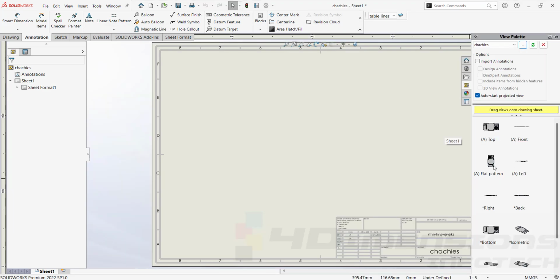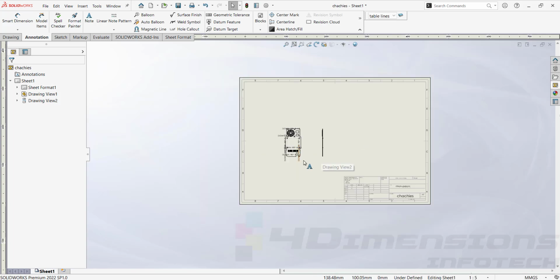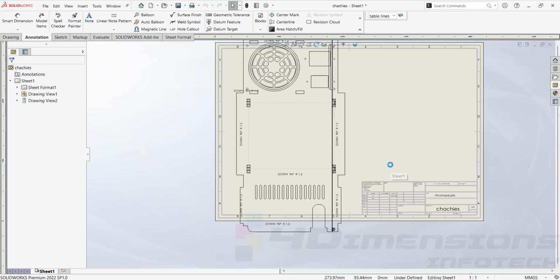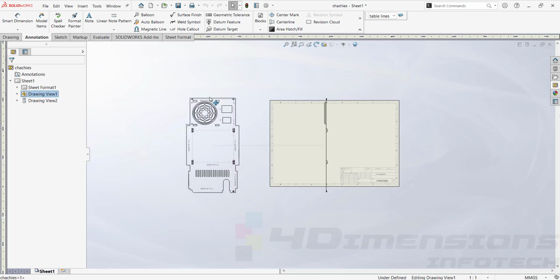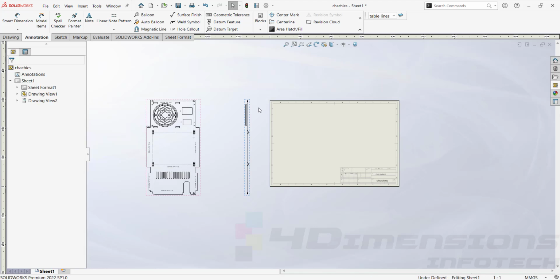And next I'm going to call here this flatten view, and we also take this side view of the flatten view, say OK. After calling this flatten view, you just need to set the scale as 1:1. As usual, flatten views are taken in 1:1 scale only, because they are going to go for laser cutting drawing also. That's why we are taking this scale here as 1:1.